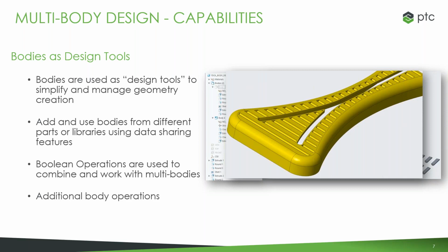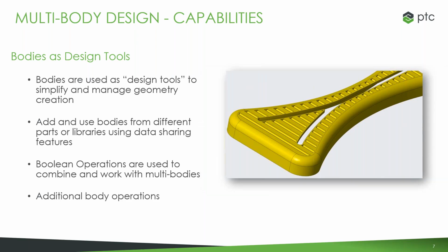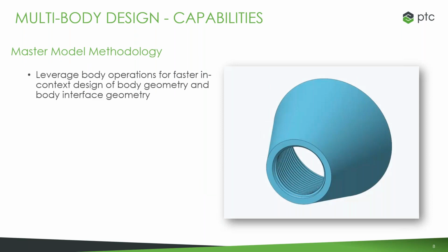We can assign appearances to the bodies, show or hide the selected bodies, and create cross sections with the selected bodies included or excluded. We can also create layer states in your model showing all or selected bodies and so on. When we add the body concept to the different approaches and concepts of Creo, it becomes a powerful feature again.